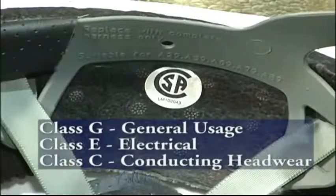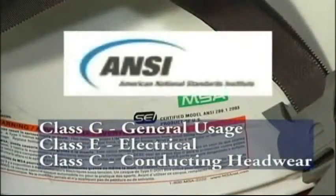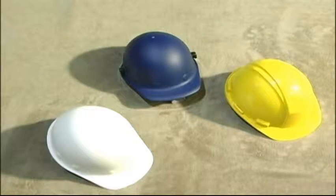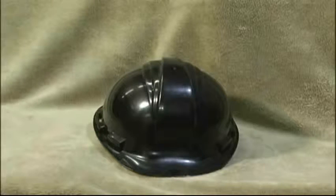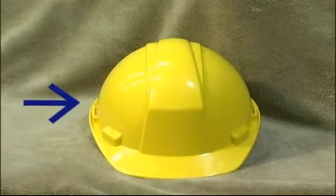There are different grades of hard hats. Each hat is designed and tested to meet CSA and/or ANSI requirements. Hard hat shells are designed to withstand various degrees of impact. There are two types of impact ratings. Type 1 is for standard impact. A new Type 2 has been developed, rated for side impact.